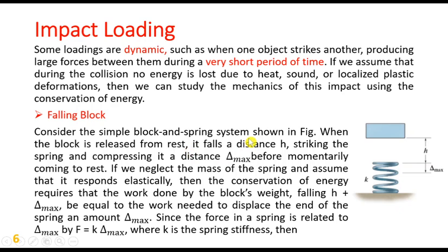Consider the simple block and spring system shown in the figure. When the block is released from rest, it falls a distance H, striking the spring and compressing it a distance delta max before momentarily coming to rest. If we neglect the mass of the spring and assume that it responds elastically, then conservation of energy requires that the work done by the block weight falling H plus delta max be equal to the work needed to displace the end of the spring